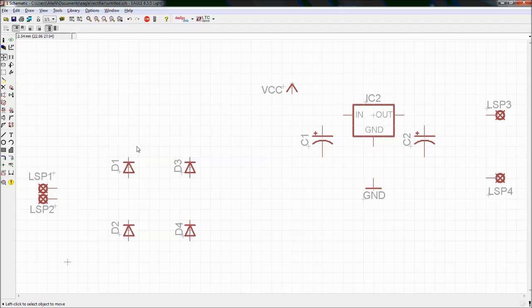Now we will connect all these components using proper wire. For that, choose this net. This is a single wire. You can say single line bus, or you can use this bus option as well if you want to connect multiple pins. Just like in a microprocessor or microcontroller, the address pins and data pins need to connect with the multiple data pins of any other devices or peripherals. In that case, we can use this bus option. But for the time being, we are using this net.